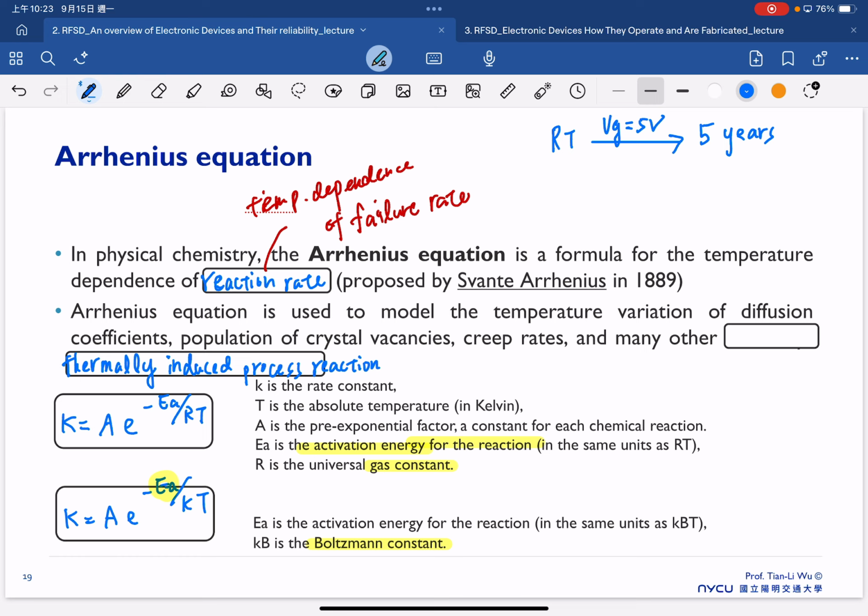So therefore we have to use what we call acceleration testing, and the concept behind it is also very simple. As we know, the temperature is always one universal factor to accelerate degradation. So what we normally do is we just raise the temperature.